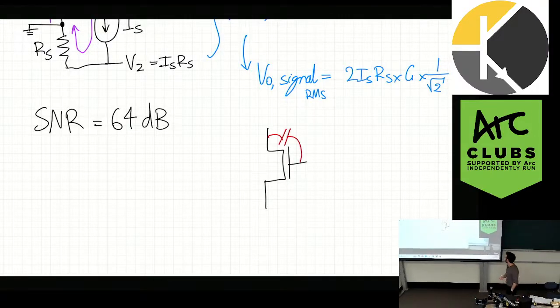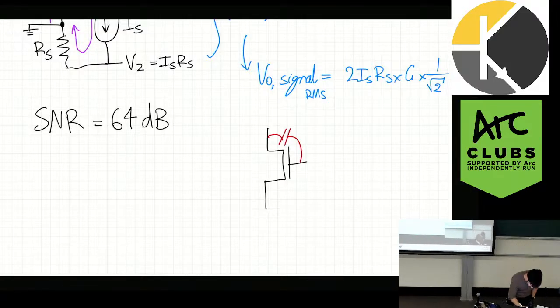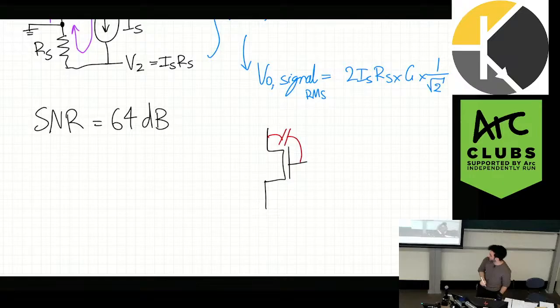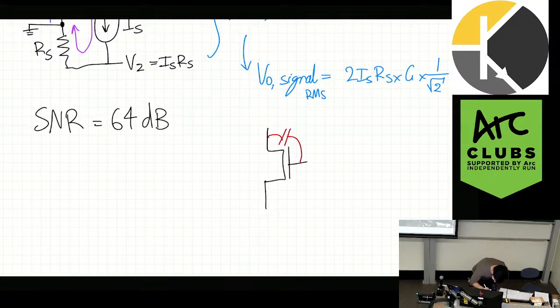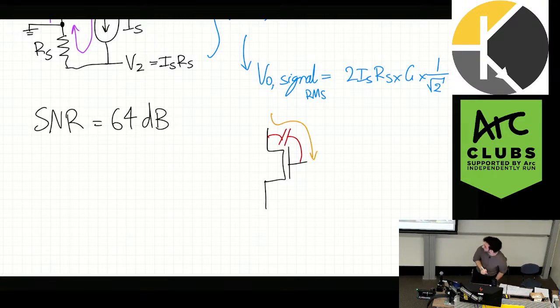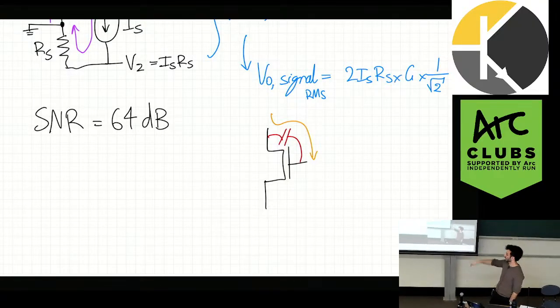This parasitic capacitance isn't a problem at low frequencies, but at high frequencies it becomes a problem. This is very similar to power supply rejection ratio, but essentially the amplifier is not behaving like it should be anymore, because the input signal is now just finding an alternative path around the transistor, right? And this is happening all across the inside of that amplifier, so the amplifiers are not behaving like they should be at high frequencies, okay? Hopefully that answers your question.